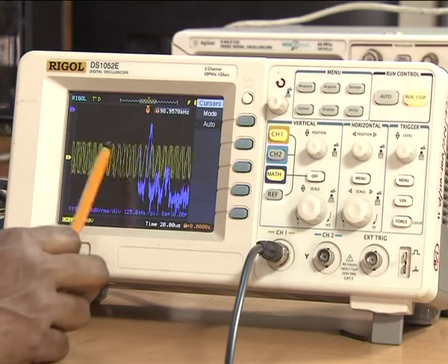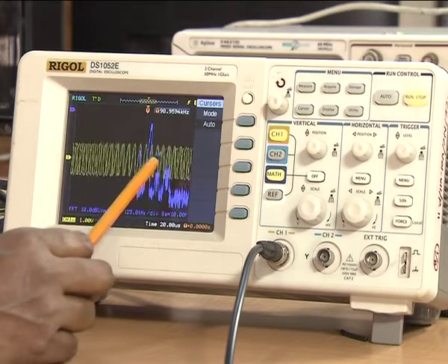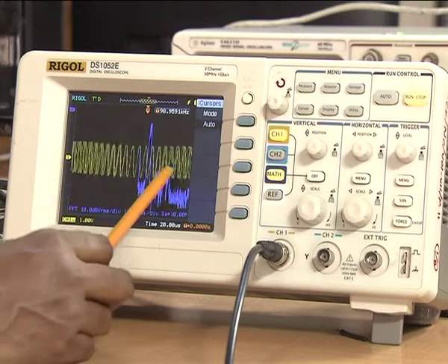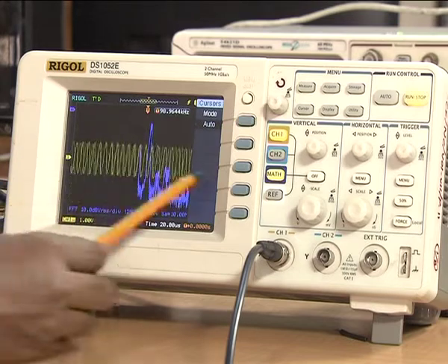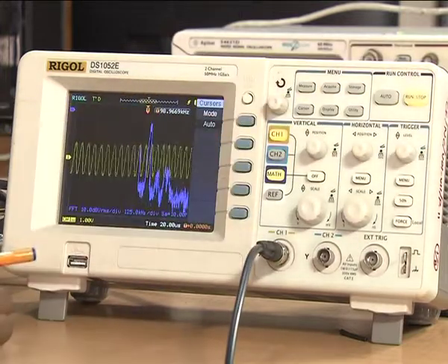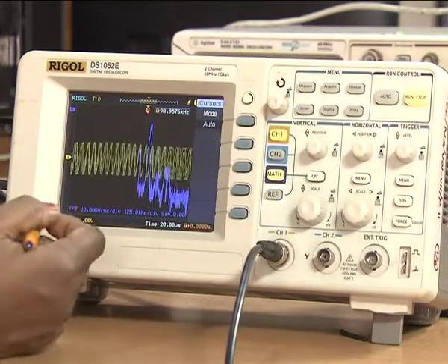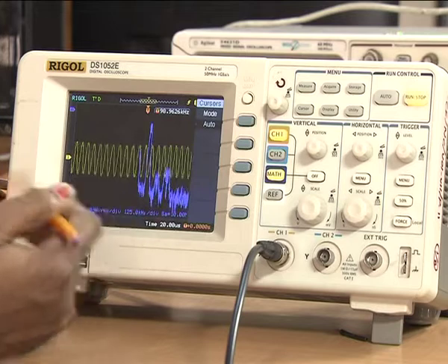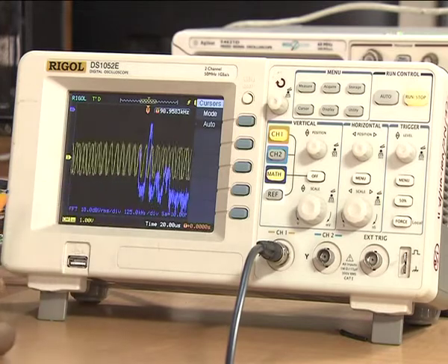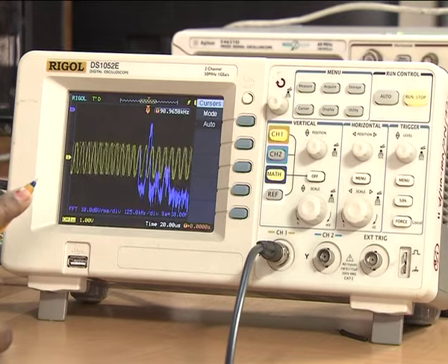For each frequency modulated waveform, you need to note down your input signal, that is your AF signal, and the frequency modulated output signal, where you can see the waxing and waning. You can make the signal stop and then draw the waveform as it looks. Next step is you need to identify the beta of this signal. Beta will classify the FM modulated signal as a narrow band signal or a wide band signal.